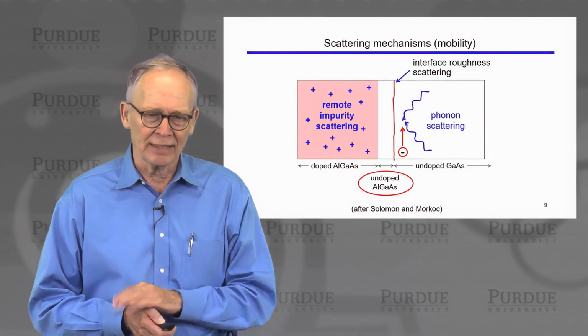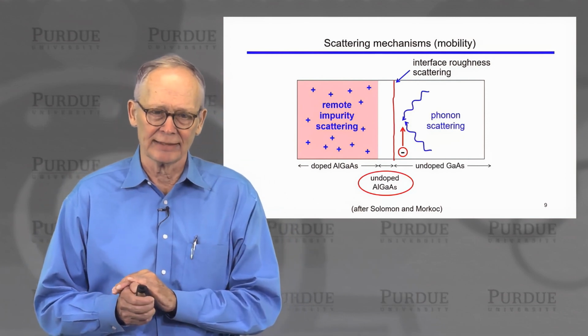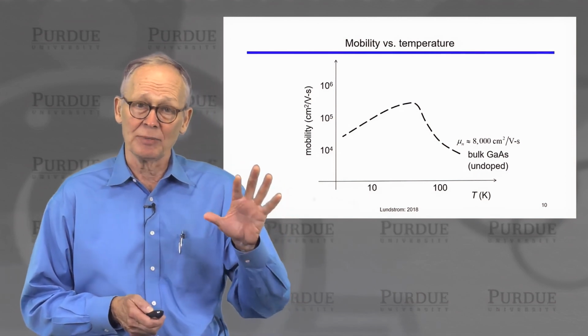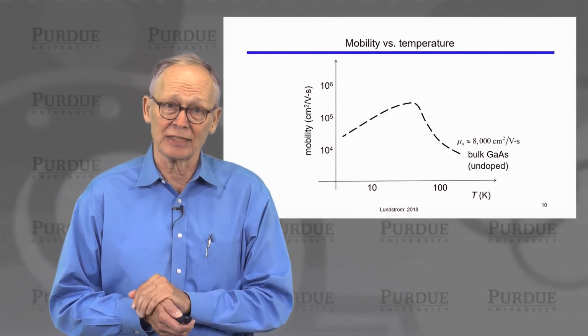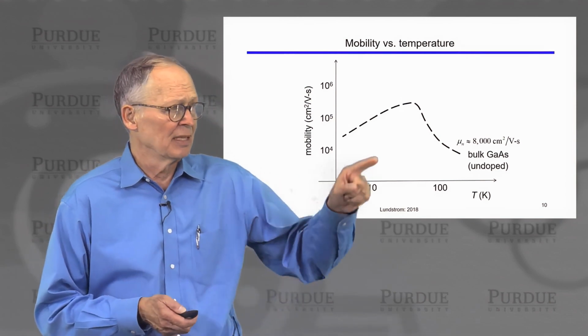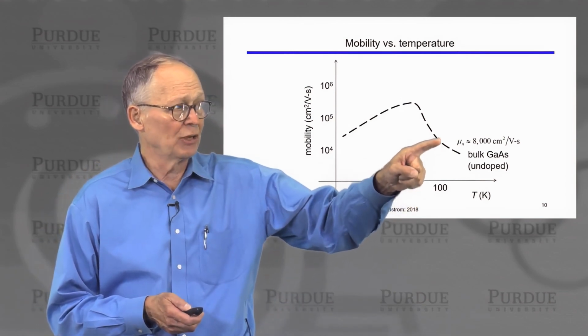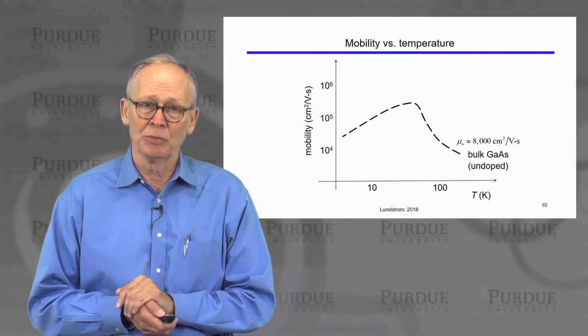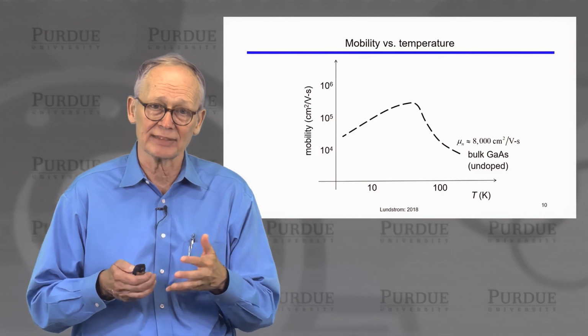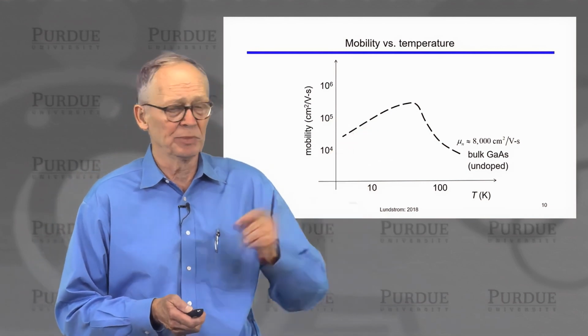Okay. So that undoped setback layer is one of the features of the epitaxy of these layers. Now, if we measure the mobility of the electrons in that two-dimensional electron gas as a function of temperature, we can see that as we cool down below room temperature, the mobilities go up because we're freezing out the lattice vibration scattering. We get higher and higher mobilities.